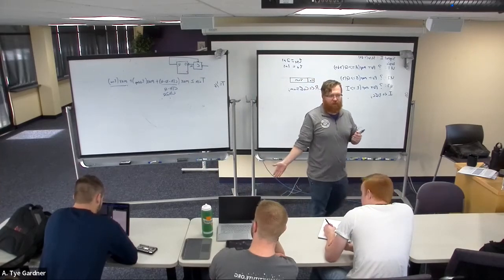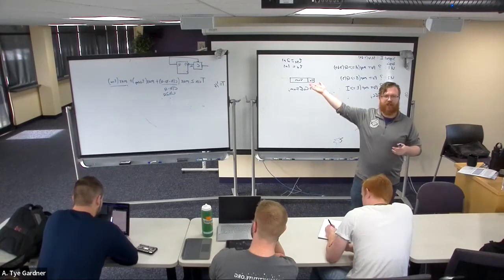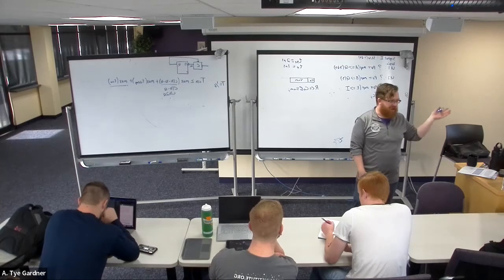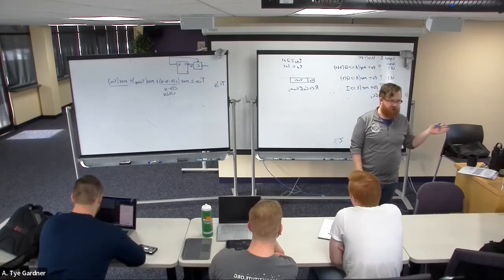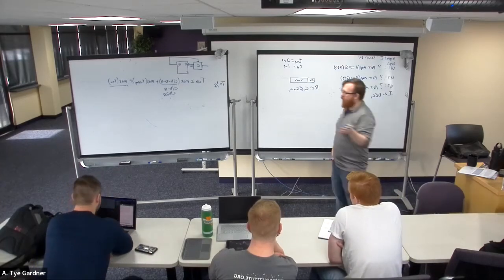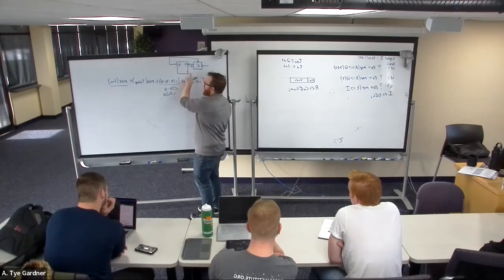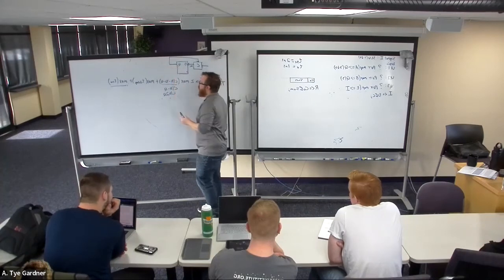Right? It's the equivalent of the gate delay, but in combinational logic. And in fact, it stems from gate delays, right? Because it's how much time does it take to propagate through those NOR gates. And the more there are, the more complicated the structure, the slower it's going to be. So what this is saying is my clock to Q is rising edge. How long does Q take?